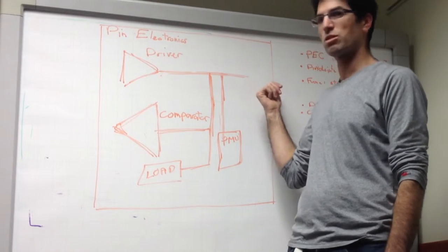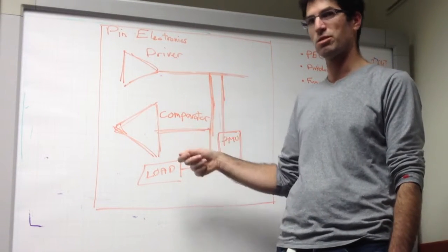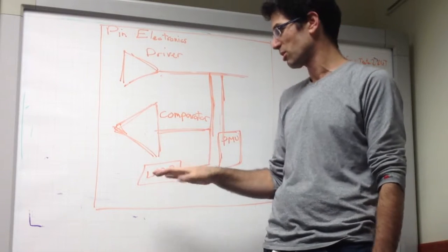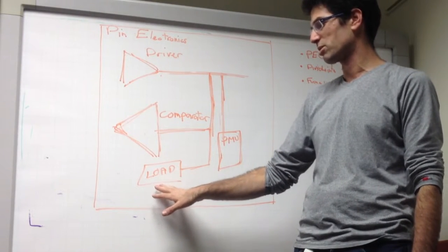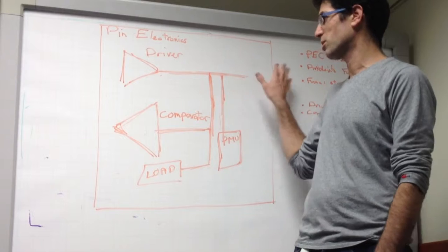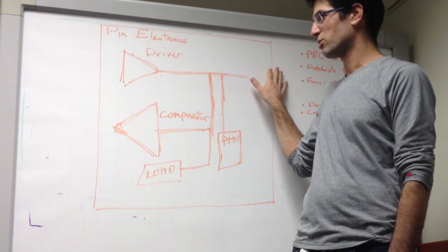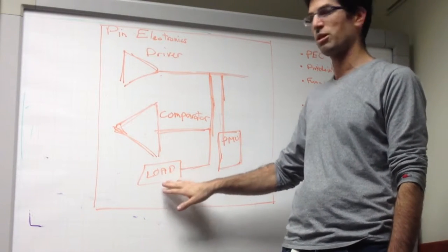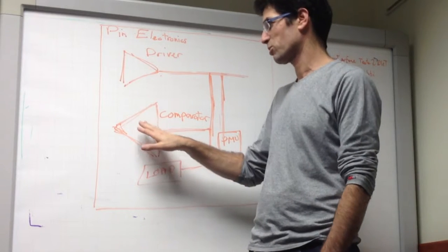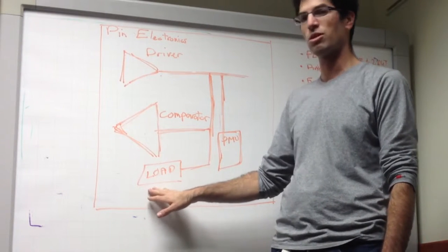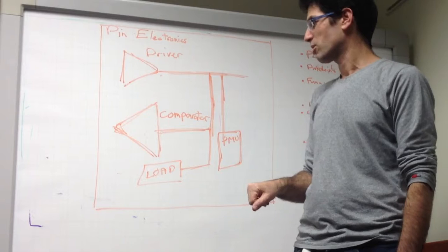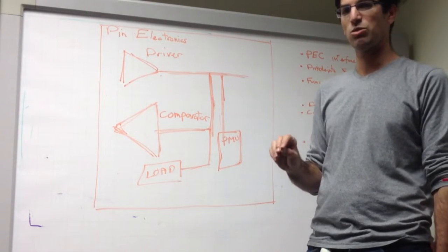So if the DUT is driving a specific bus that has certain characteristics, we can simulate these characteristics in the load to make sure that the output levels are not only logically correct, but also strong enough. So the comparator will be valid within the load conditions. This is the functional side of it.